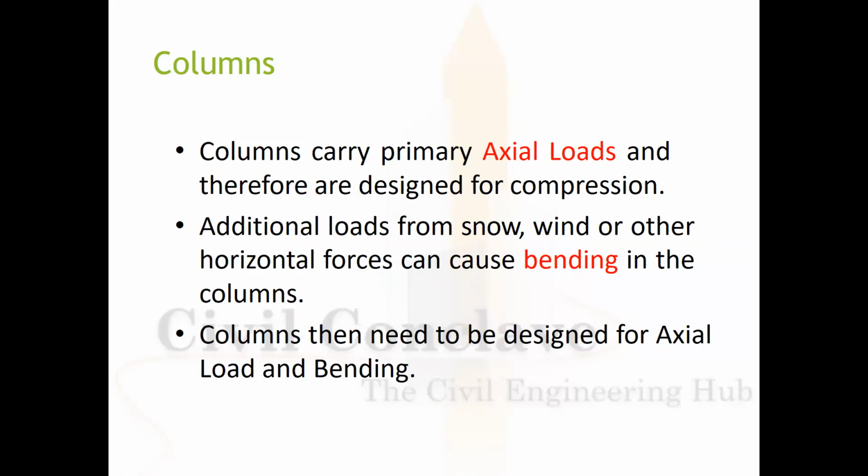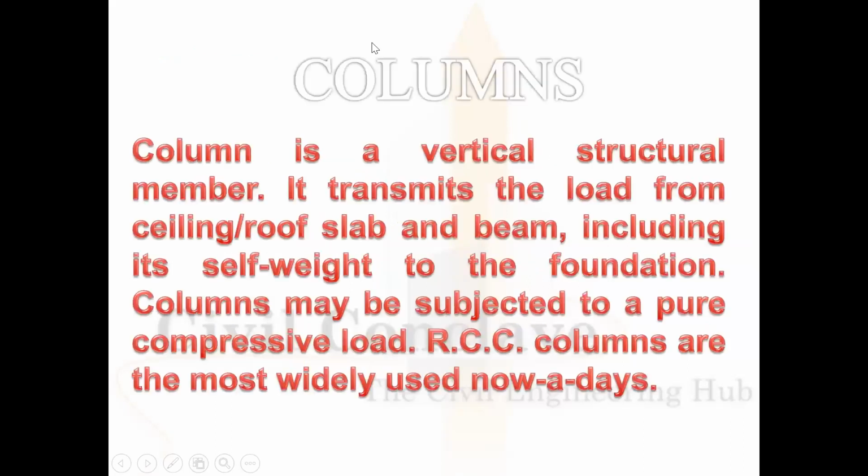Columns. Columns generally carry the axial loads and are therefore designed for compression. Additional loads, when there is snow or horizontal forces, can cause bending in the column. Columns then need to be designed for axial load and bending. A column is a vertical structural member. It transmits the load from the ceiling, roof slab, and the slab, inclusive of its self weight, to the foundation.